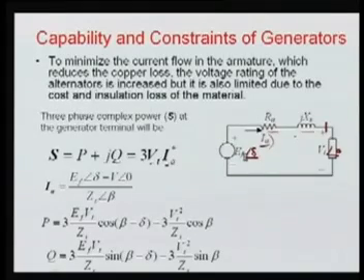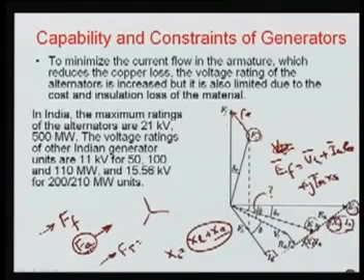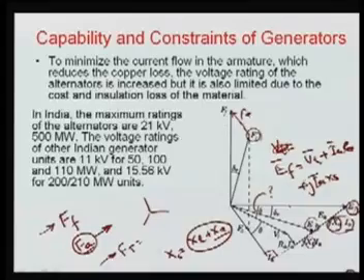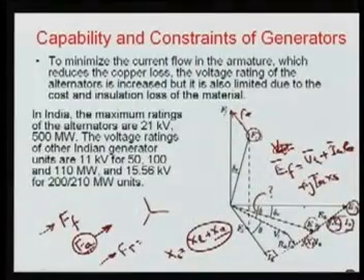Now you should be very careful and you should know what this delta is. This delta is known as your torque angle or sometimes power angle, because this is the angle between the two voltages, that is, the terminal voltage and your field voltage. So this is called load angle, and it is different from your power factor angle.